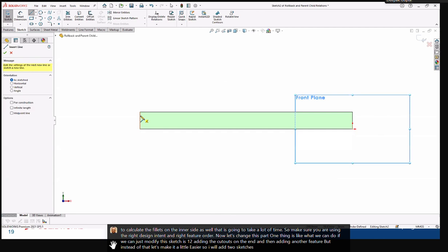So instead of taking your mouse to this box, in case you have not pre-selected a center line, the moment you select your entities, you can just simply right click and SolidWorks will jump onto the next window. This trick will be available for many features and you can explore them. Let me show it once more. Look at the cursor, it changes to an enter, right? So you can see the right click is acting as an enter button. So I'll click on it and then click OK.